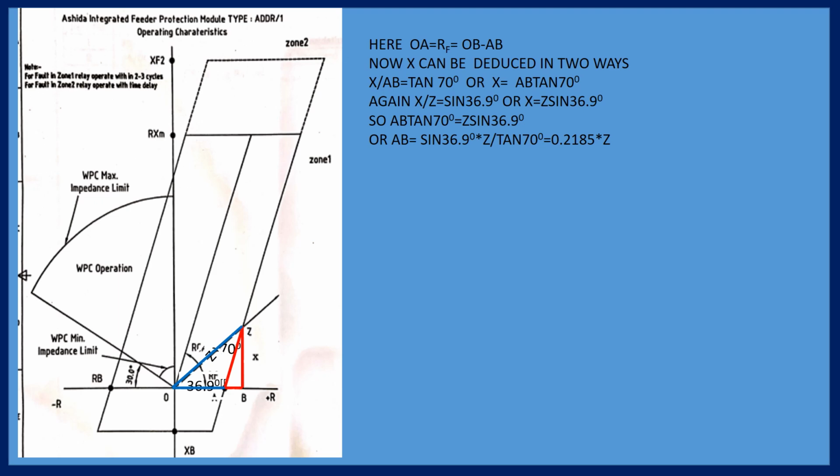So next importance is the discharge rod, earthing rod. You have to protect from two ends, and the distance they have told is 100 meter at site. Within 100-meter distance you have to put two discharge rods.